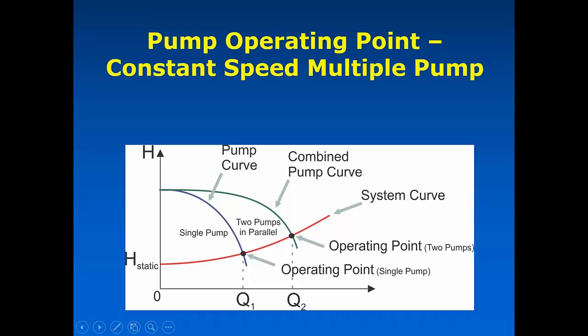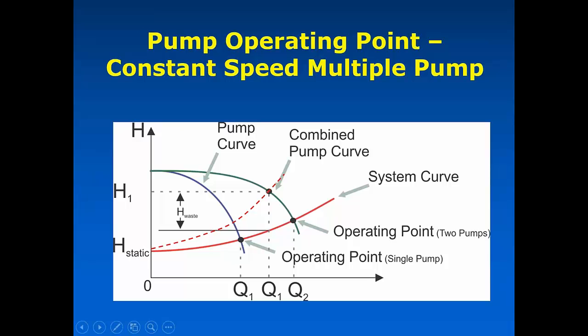So the option, if you had a constant speed pump, is bring more pumps online. You can have pump curves for an individual pump, and if you combine them together, it works basically the same way. You have this combined here. If you had a couple of pumps that were defined by this particular curve each, and here's our dynamic and static head together, the system curve here, we can see that you can reach a higher point on that curve if you have to by operating two pumps together.